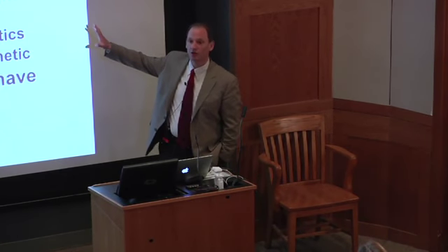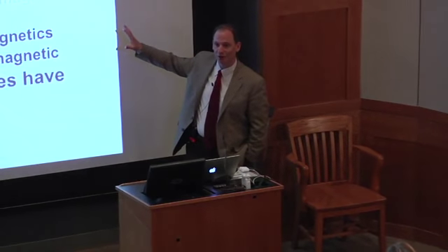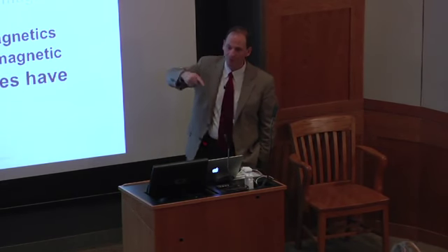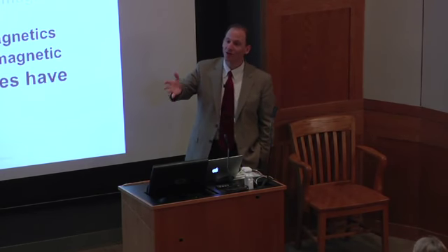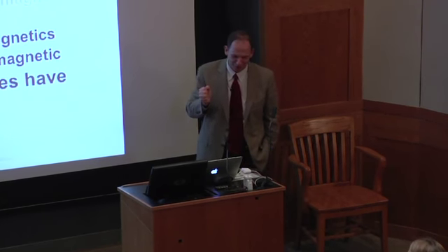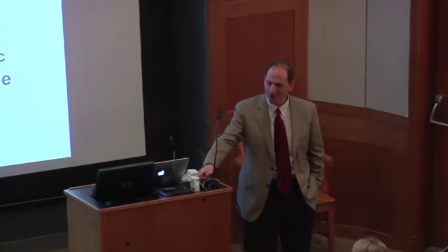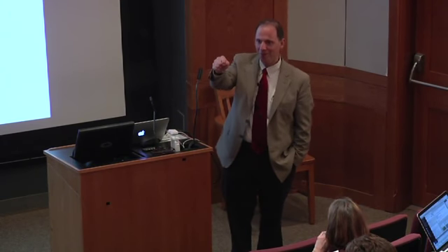You're correct that the one I showed you didn't actually get a very good waveform, but keep in mind, that's 0.9 power factor. That's what people want to get to. If I showed you what the power supply for my MacBook here was doing, you'd shrink in horror. It actually looks like an impulse at the top of the line and an impulse at the bottom of the line. I don't remember what the power factor is, I've measured it, but it's well below 0.5, and it really is causing those problems.